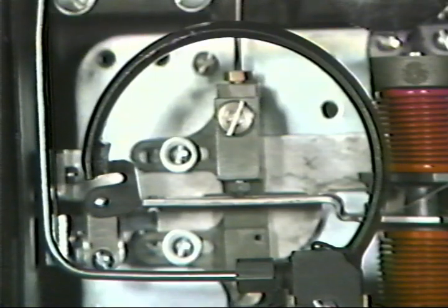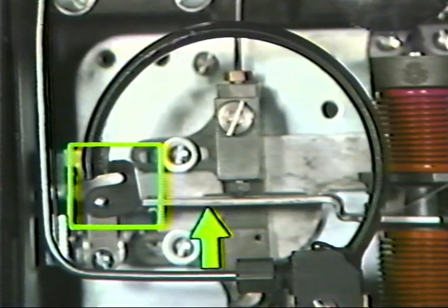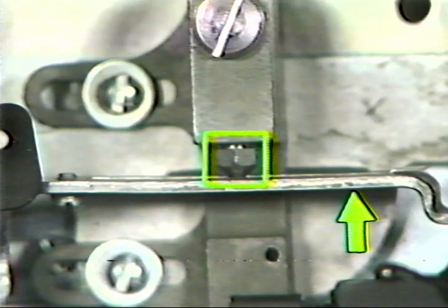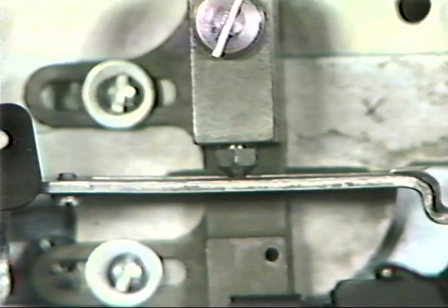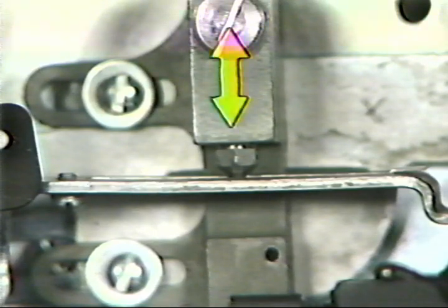Again, we can compare the illustration of the controller we've just seen with an actual reset controller. A Bourdon tube is the controller's input mechanism, which measures the signal from the process variable. The tip of the tube is connected to a beam. The other end of the beam and a nozzle make up the error detector mechanism, where the measured signal is compared to set point. For this controller, set point is developed a little differently from the ways we've seen so far. Instead of using a spring to establish the proper distance between the flapper and nozzle, this controller's set point is adjusted by actually moving the nozzle in relation to the beam.